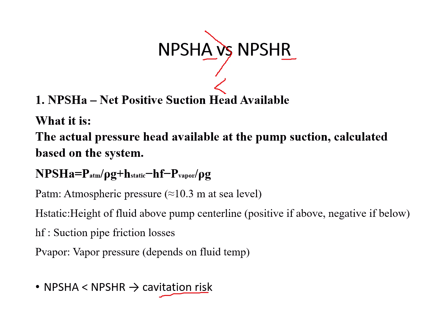You can also use larger suction pipes, and that's why you can notice in centrifugal pumps that the suction pipe is always one size larger than the discharge. This is just to ensure that we are away from the cavitation phenomena. And of course, you can reduce the number of fittings at the suction side to improve the net positive suction head available.